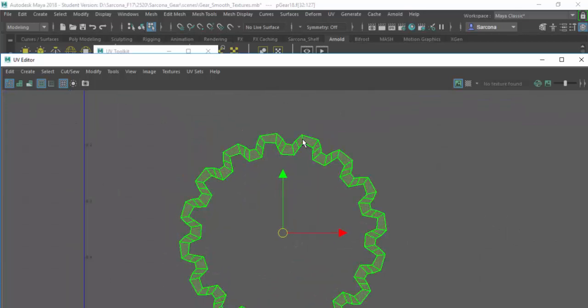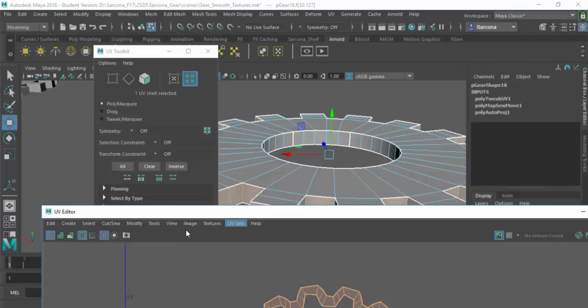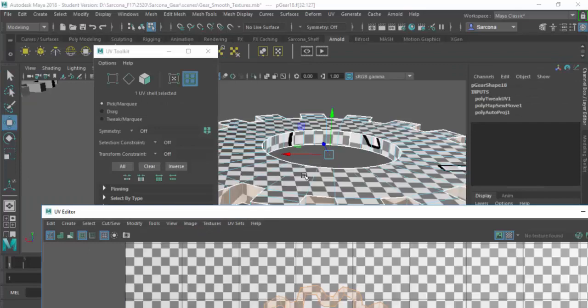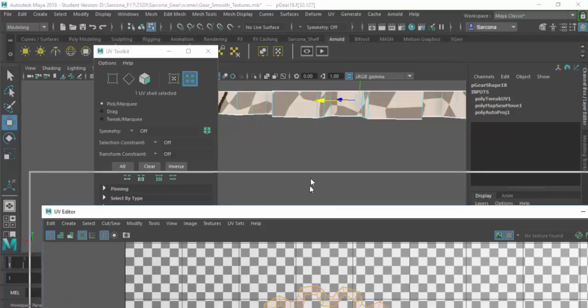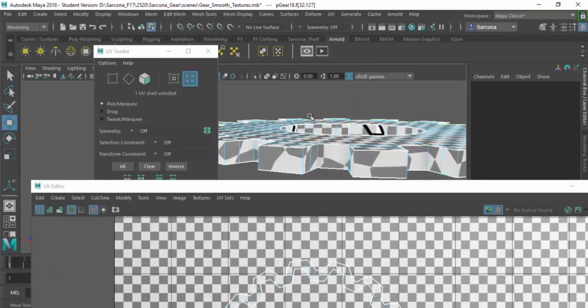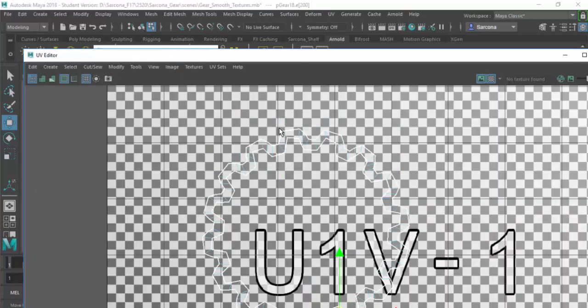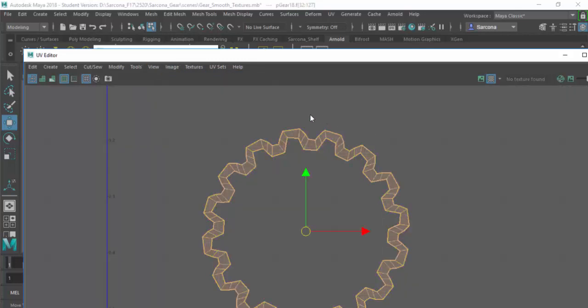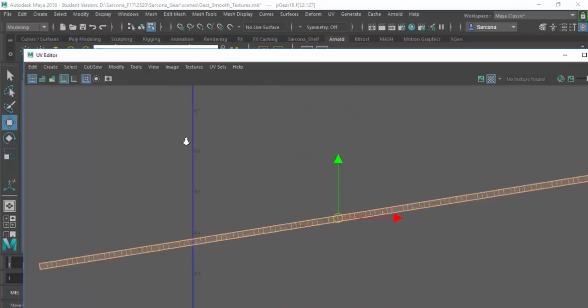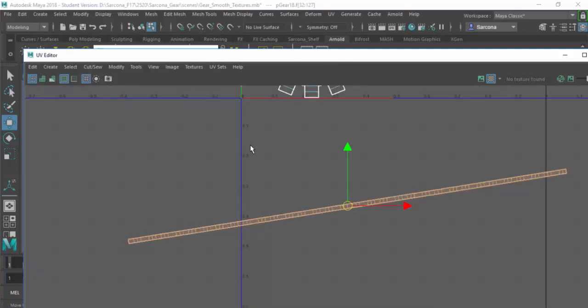Now, it doesn't look very pretty, and I'm assuming that if I were to turn my texture on, my checker map, that it's going to give me some warbly type stuff, and that looks pretty ugly. But it's nothing to worry about, because all I have to do is go to Edge, find an edge, whoops, cut the edge, hide the image so we don't have to blind ourselves, and then just do the unfold again. And see how the unfold just like, boop, a perfect strip. That's all we had to do, okay?